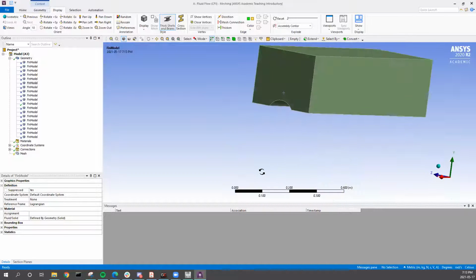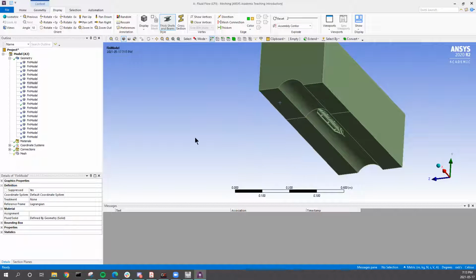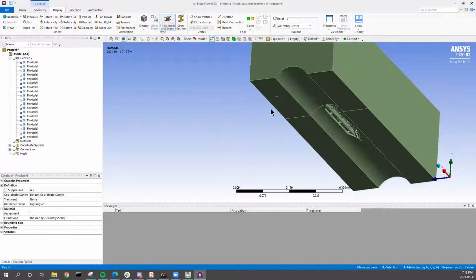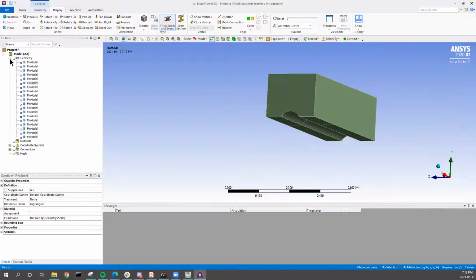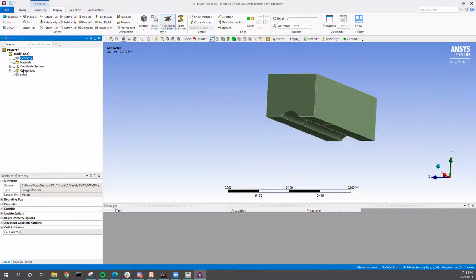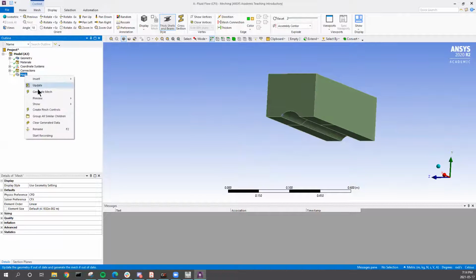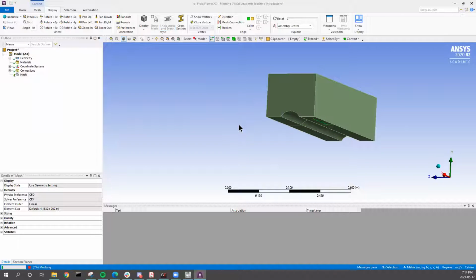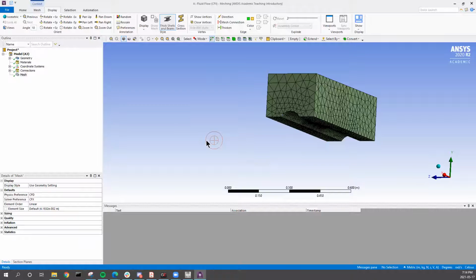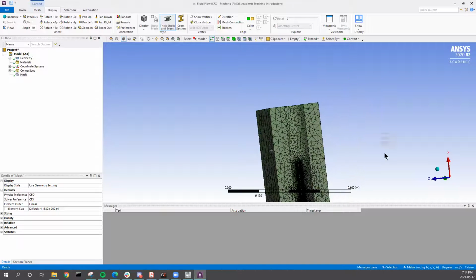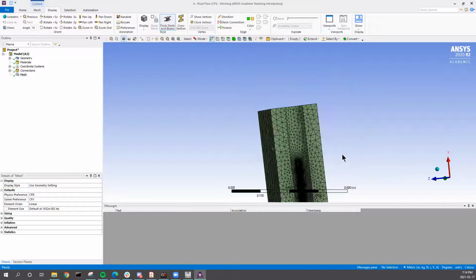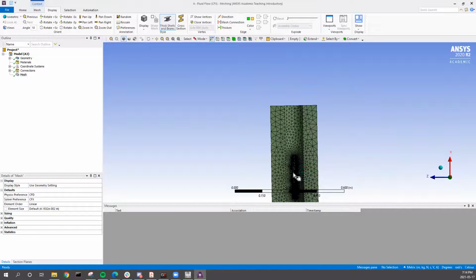And basically in CFD, you model the fluid domain. So FEA is the actual solids, and then CFD will do the fluids. So we have our geometry. There are no connections or anything. Just start by generating mesh. We're all on student licenses here, so I don't really know how well we can get the mesh, but the finer the mesh, the more accurate usually.